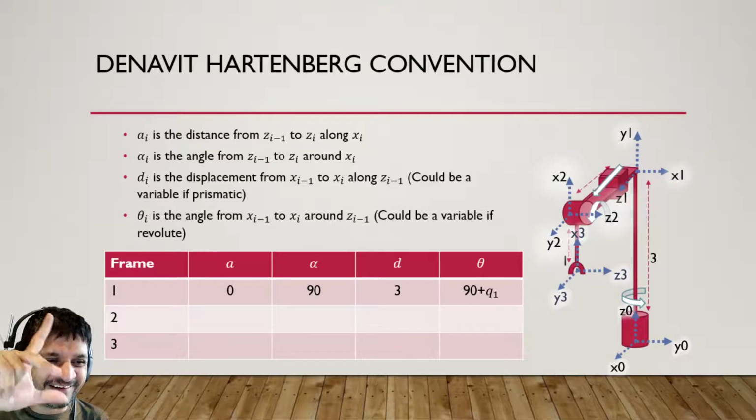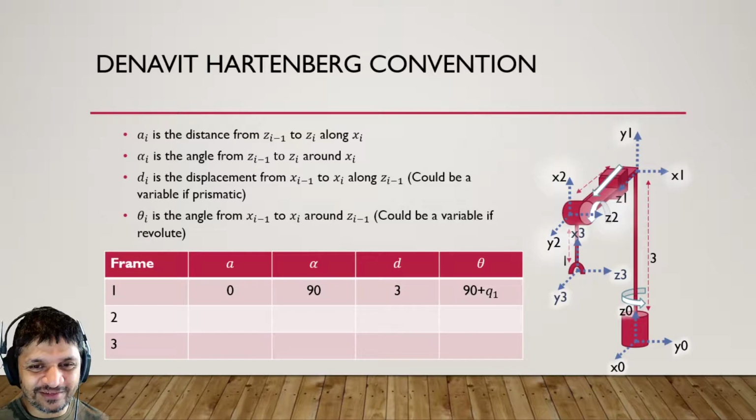I don't know, this is hard to do because the camera is not facing the right way, it mirrors everything. So you've got this axis that looks like this, but if I rotate the bottom frame, then the whole thing rotates, so my axis is no longer where it's supposed to be, right? So if the joint rotates by the value q1, then my theta will become 90 plus q1, because I'll need to rotate the 90 just to get the axis to align in the first place, and then by another q1 that accommodates for the rotation I just did. Okay, I hope that makes sense.